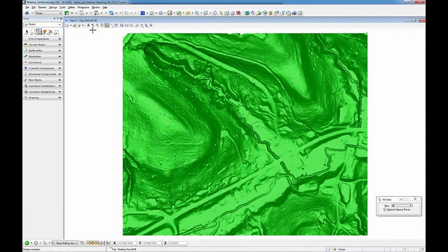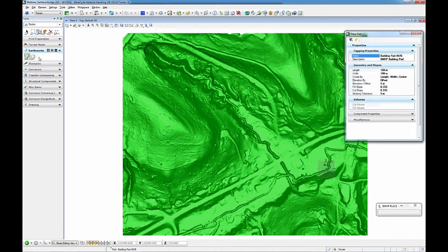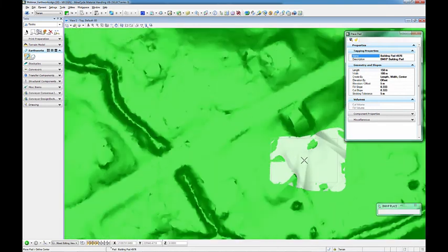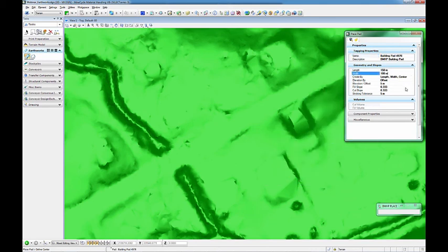MineCycle Material Handling earthworks capabilities are in the form of site pad tools. Pads can be easily created by simply selecting a point and an orientation. Length, width, and independent values for cut and fill slope can be specified, or the default values accepted.